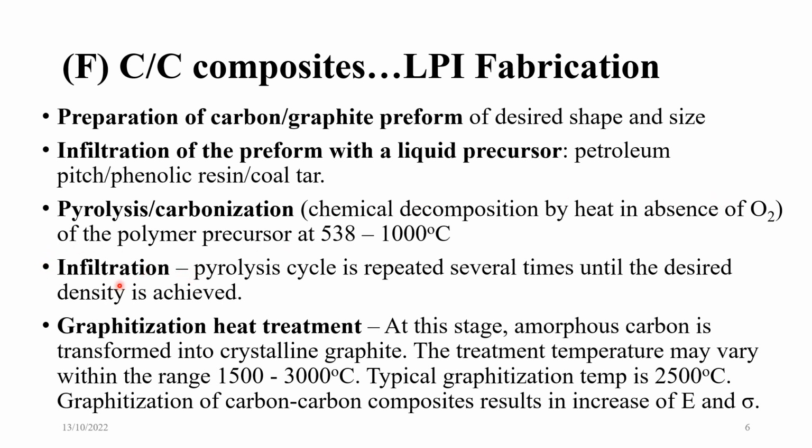Next is the infiltration step. Pyrolysis cycle is repeated several times until the desired density is achieved. So this thing you have now heard multiple times, 100 times for each fabrication method of ceramic matrix composites. Improve the density, increase the density. We have to enhance the density. The densification is very important.